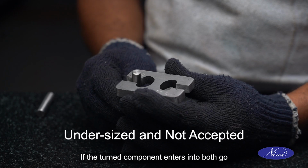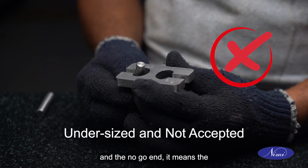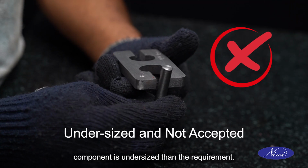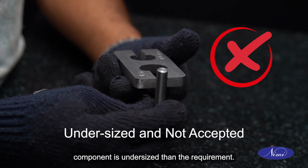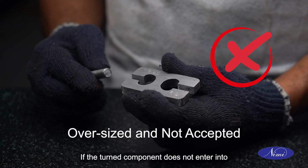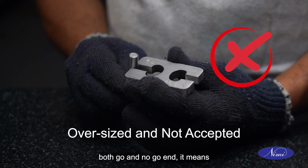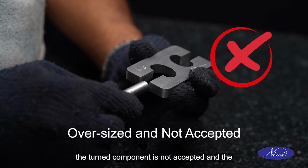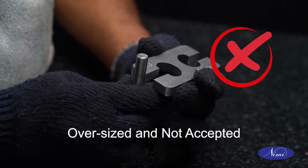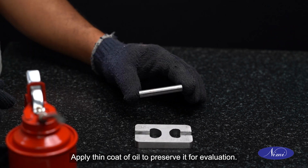If the turned component enters into both go and the no-go end, it means the turned component is not accepted and the turned component is undersized than the requirement. If the turned component does not enter into both go and no-go end, it means the turned component is not accepted and the turned component is oversized than the requirement. Apply thin coat of oil to preserve it for evaluation.